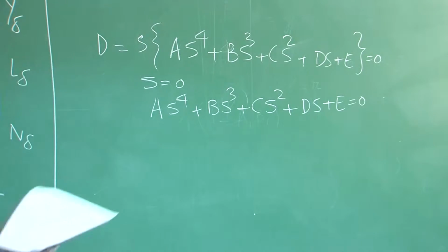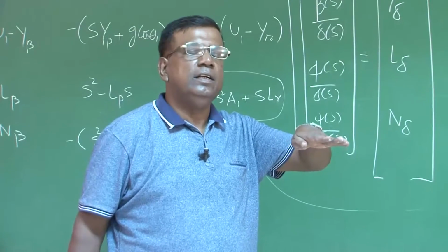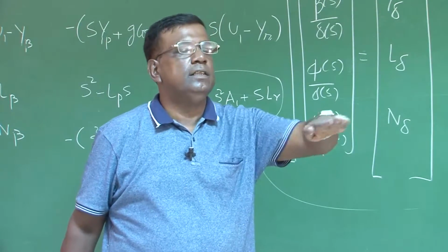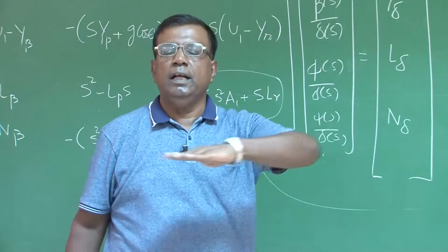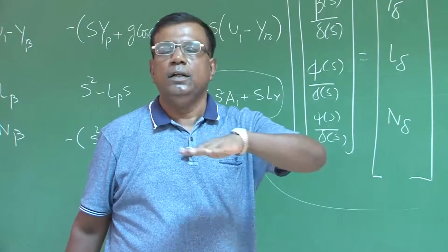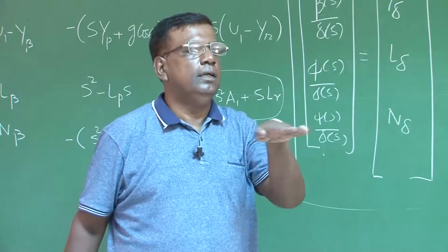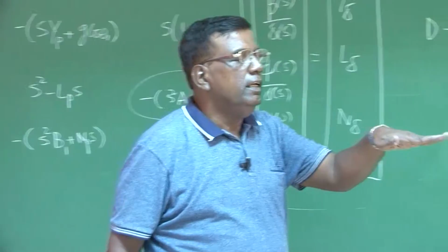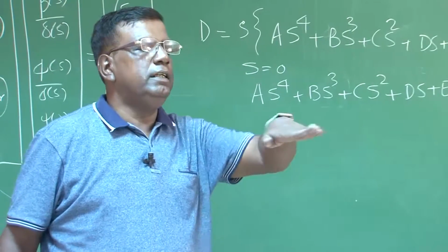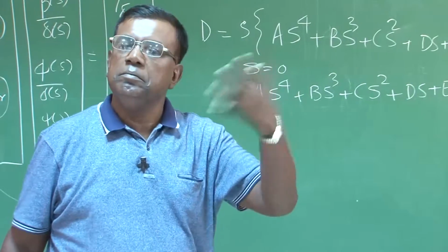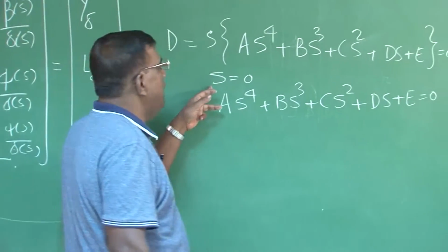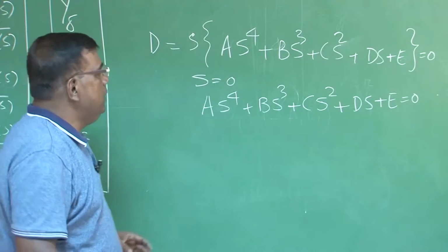S equal to 0 is the case in the lateral directional, it is like neutral stability with reference to psi. See, the airplane goes like this, goes like this, aerodynamically they are neutrally stable, like no change, right? Okay, no resistance, because for an airplane it is a relative airspeed. So flying at psi 2 degrees, psi 3 degrees, psi 4 degrees is the same thing. So S equal to 0 suggests that, so we neglect that, okay, we understand.